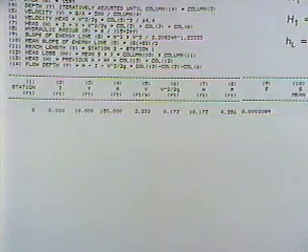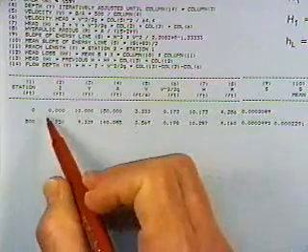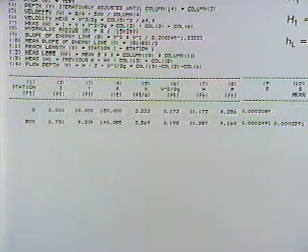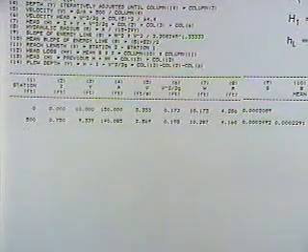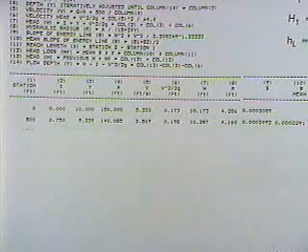So once you've got the depth, you can compute everything from simple equations. Now the problem is we don't know the depth. And so what we're doing here, the first line is just to give us basic data, and so we're working upstream now. So at the end of the channel where it empties into the river, the depth is 10 feet.